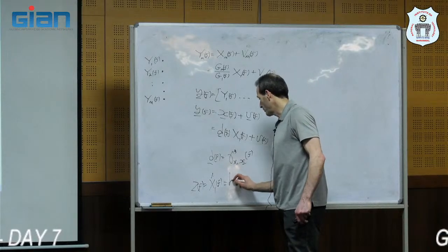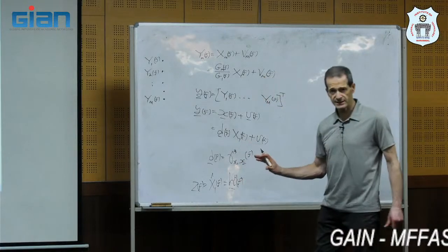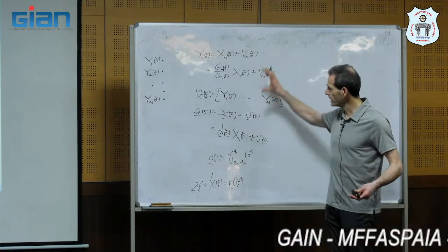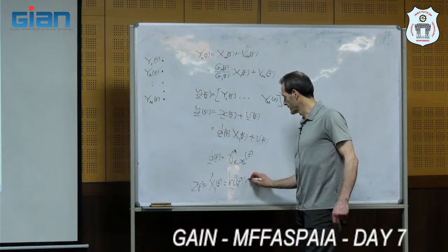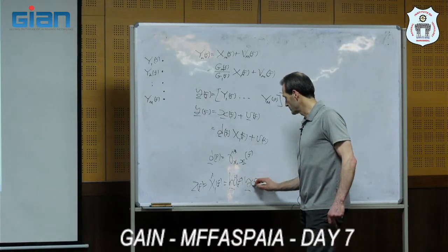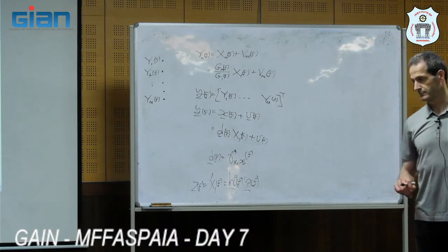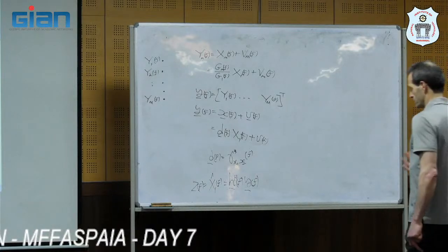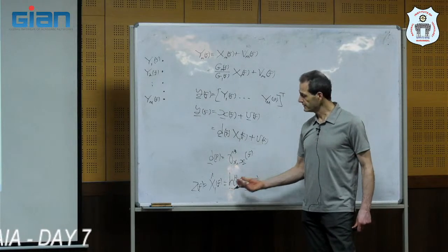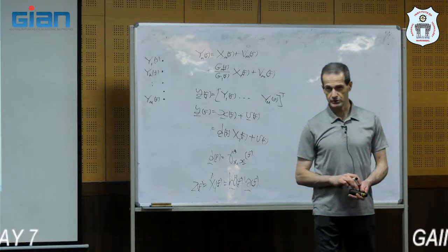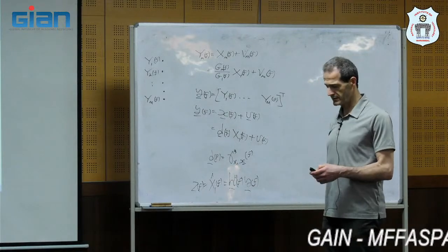Linear filter. Okay? So we saw that we can write it like this. We need to find an optimal filter of length m. For each frequency this filter is different, of course, because we work independently for each frequency. So we optimize it for each frequency and multiply it with this vector of m measurements for the frequency f. Okay? So in order to find an optimal filter for each frequency, we need to define the performance measures.